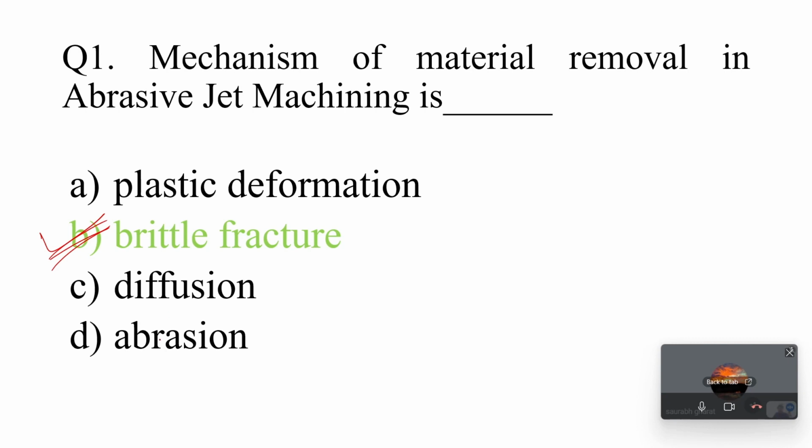Diffusion is a different process, where heat is involved, like sliding or grinding, and material removal is not included. In abrasive jet machining, plastic deformation is also not included. So only brittle fracture is the correct answer. Considering all the other options, brittle fracture is the only correct answer.